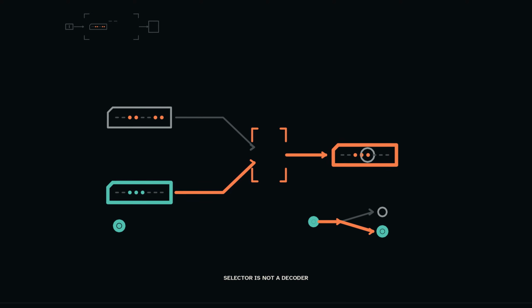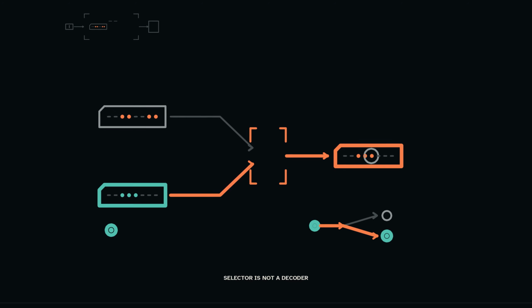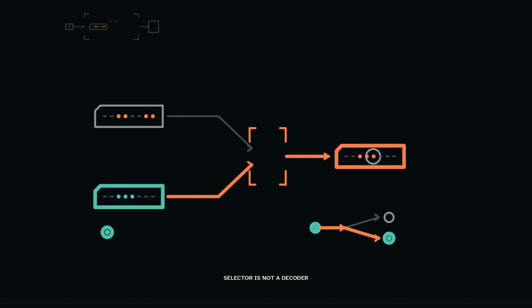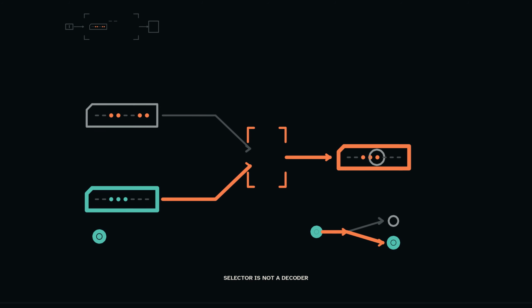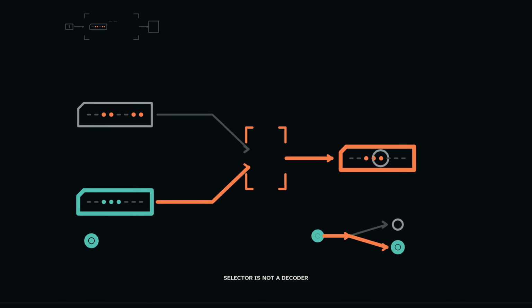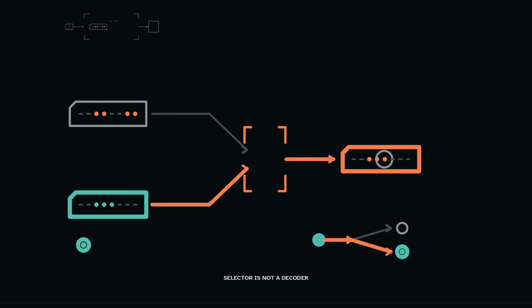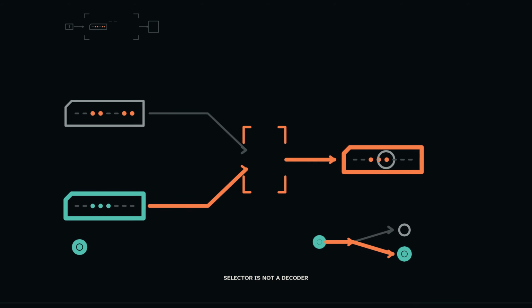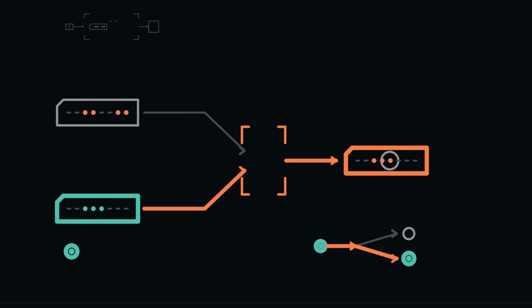Replicate the proved 1-bit selector 8 times. Align the copies with the notched carrier and share the same select value across them. Each copy chooses the corresponding position from byte A or byte B. No position crosses into a neighbor, and the notch preserves left to right order. The result is an 8-bit selector. Scaling has repeated a proven relation in parallel. It has not introduced a new rule or treated a byte as one indivisible physical lump.